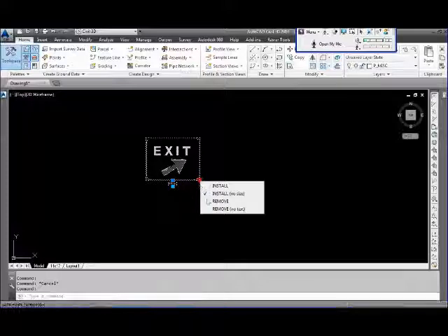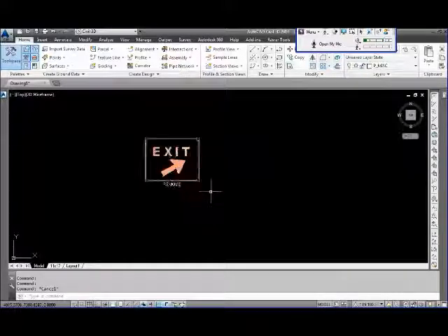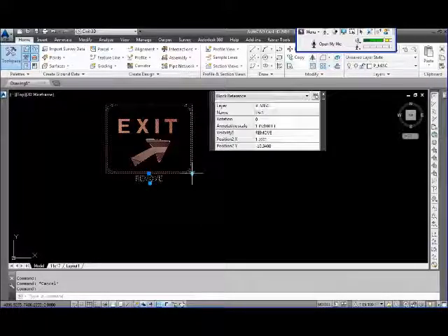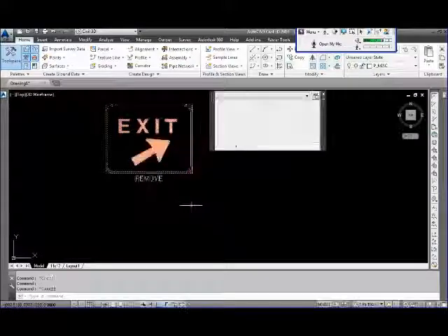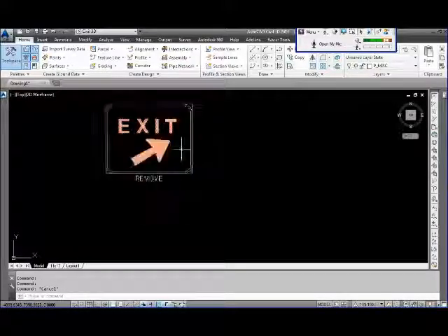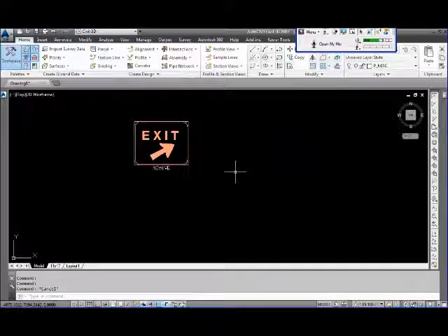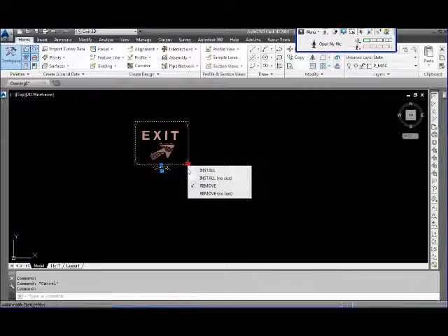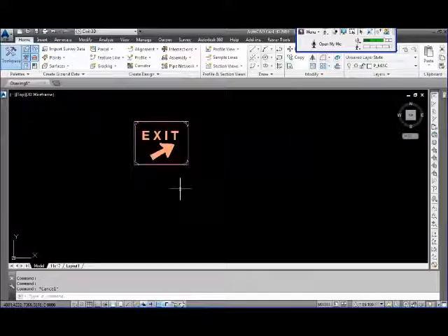That's really nice. Now, Remove signs. The first one is just Remove for the visibility state. You'll have a remove text on the bottom, and this is put on an existing layer, so that layer plots as existing. So this remove could be an existing sign or whatever, but it basically puts it on an existing layer, which is extremely helpful. And then the last one is Remove with No Text, so the remove text is suppressed.